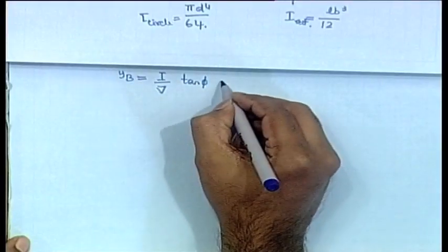Of course, when you derive the equations, we will see a static stability curve, which you draw for the whole ship from 0 to 90 degrees, fully tilted, but it is not in practice. What you generally see because of wind is 0 to 10 degrees or maybe 15 degrees maximum. So, in these cases phi is really small. These derivations that I am doing are only for ships. You cannot generally extend them to all types of bodies, such as small rectangular bodies that tilt fully. But for the ship we can say that y b is equal to I by del tan phi.